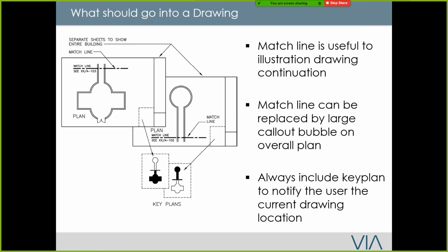Right now, I do a lot of key plans for sections, because sometimes you're going to have hundreds of sections that get overlapped. So what we want to do is show people where this section is in relation to your key plan. Okay, always do it because it's a very useful tool. In probably a future session, I'll explain how to create a key plan. It's not using detail lines, it's actually using real Revit objects.